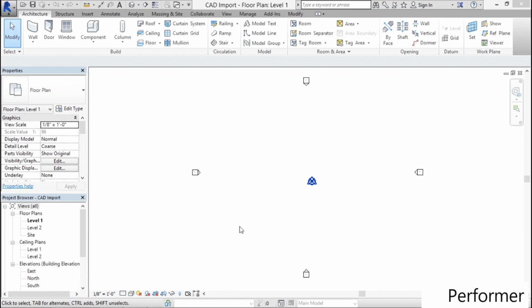I'm not really sure why they have that limitation, but I do know it has something to do with the differences in the way that Revit calculates precision versus the way other programs like, say, AutoCAD calculate precision. It's really not terribly important that we know exactly what those details are, just so long as we understand that this 20-mile radius is a good limit to stay within. So to illustrate what happens when you try to bring in a file that's bigger than that, I've got a few CAD files that we can import in and see the consequences.